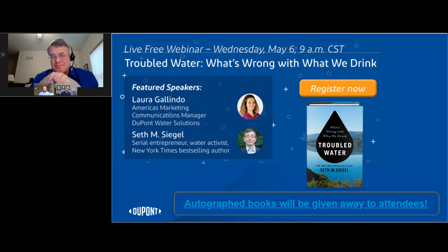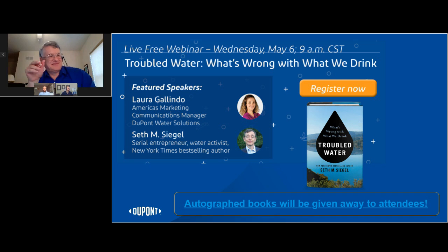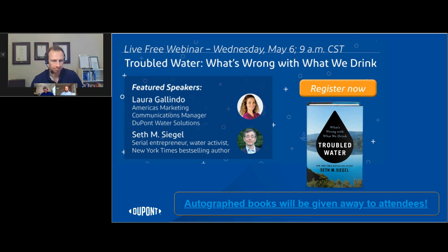All right. Well, Kevin, do you have any final questions before we wrap up? So, yeah, there's one more that I'll address quickly. It's about the difference between trains and skids in the UF model. So a train is any group of modules that shares a common valve stack, shares common instruments, and a train might be made up of multiple skids.